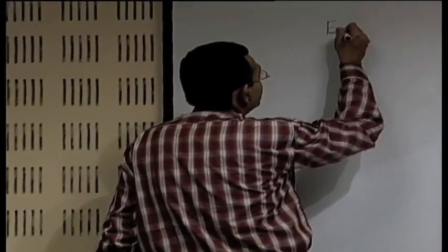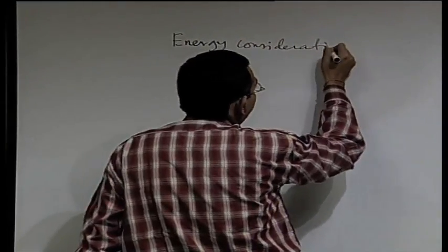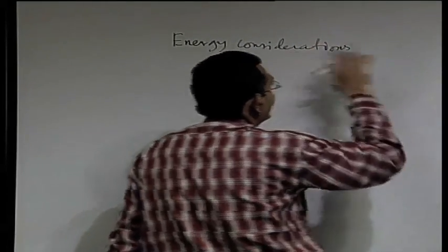Now here we are seeing that even if we might be tempted to use the Bernoulli's equation, because of certain losses it may not be directly applicable, and there might be certain errors. So these losses must have some relationship with the energy consideration in the pipe flow. Let us look into a bit more detail of the energy considerations in pipe flow. The objective will be to figure out how the head losses are related to the total energy balance.